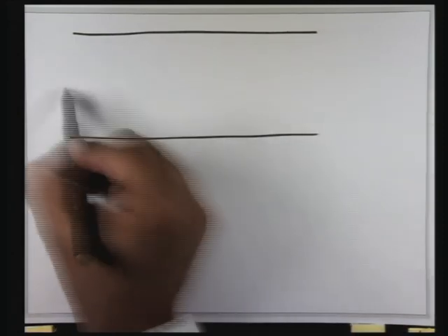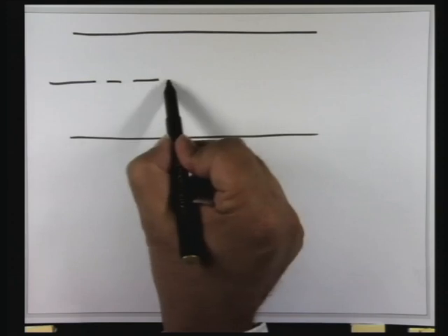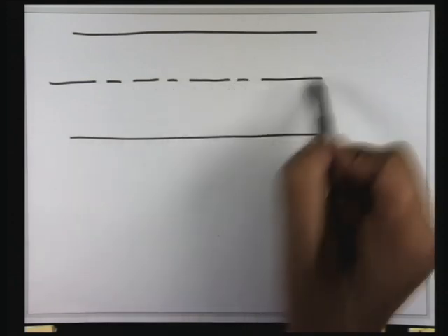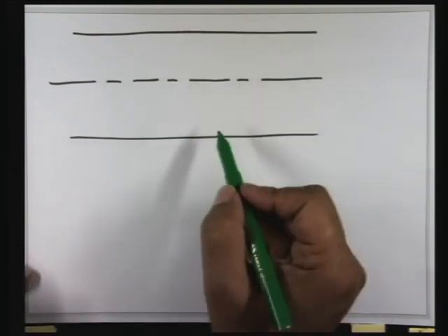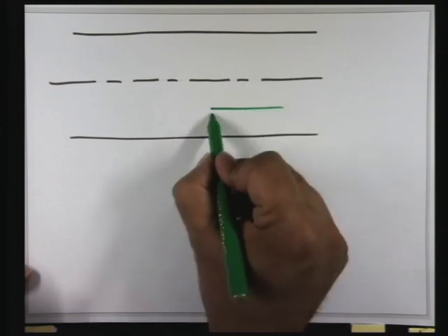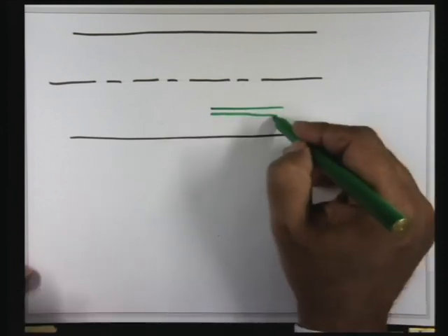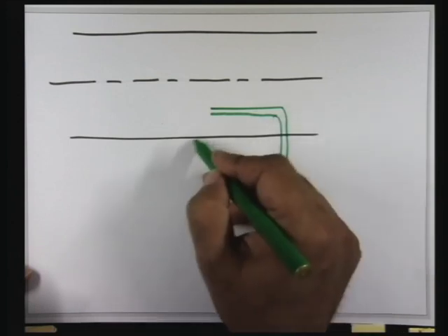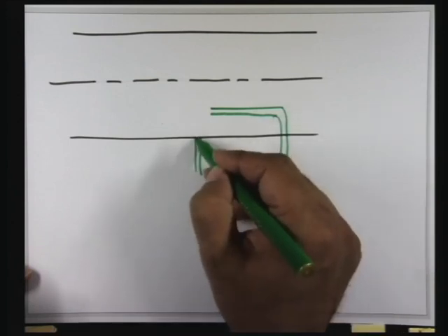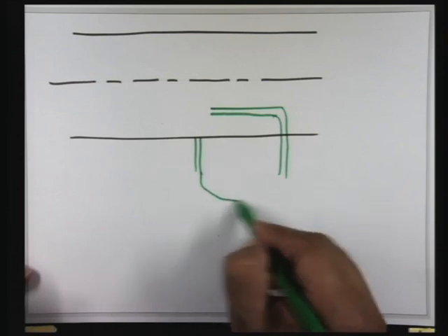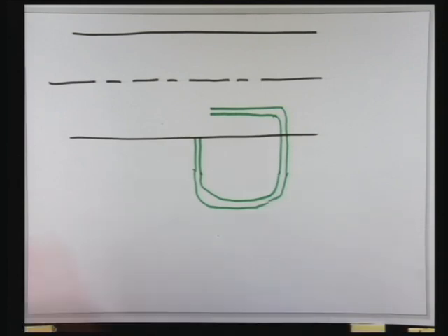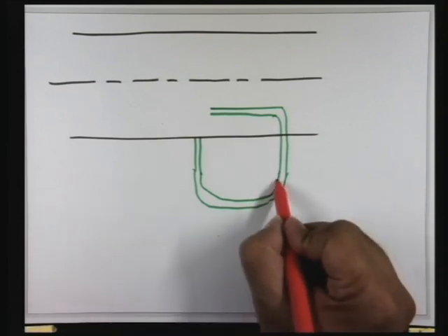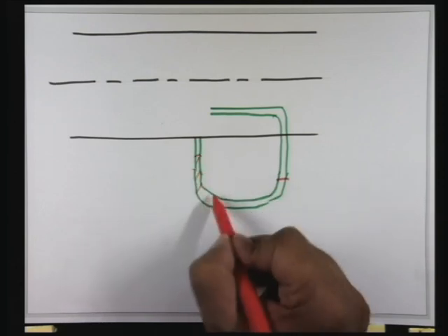Suppose this is a circular tube and you have the center line here. Now you could have your pitot tube, and you can traverse the pitot tube across this section. So you can have the tube here, which is not on the center line. And what you have to do is make this what is called a static pressure tap, in the wall. And you need a different fluid here so that you have a manometer deflection.